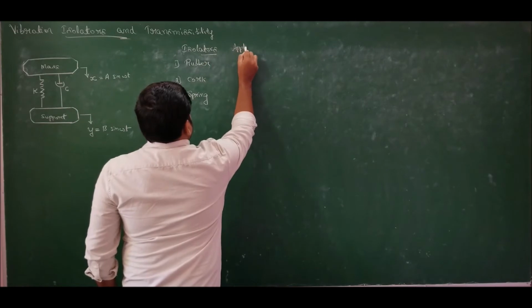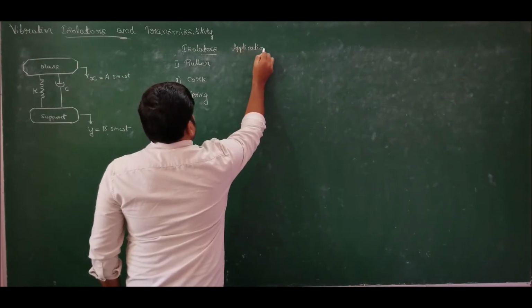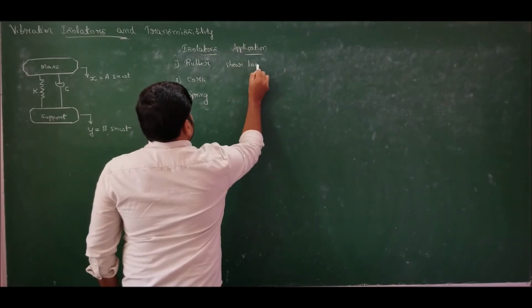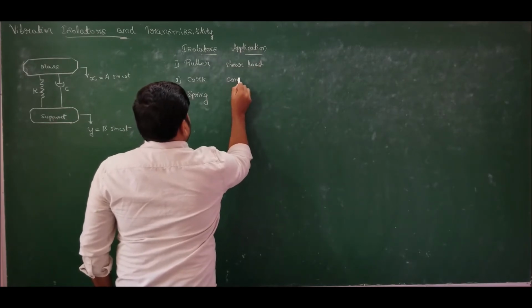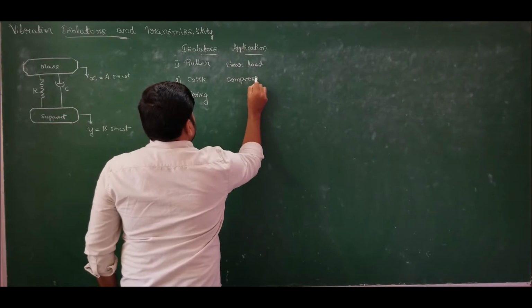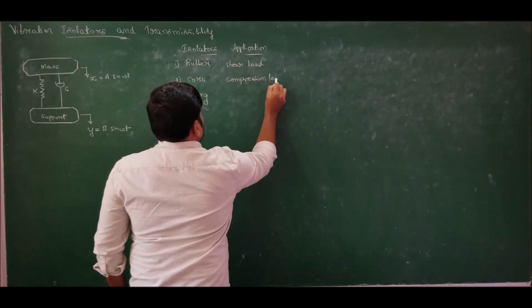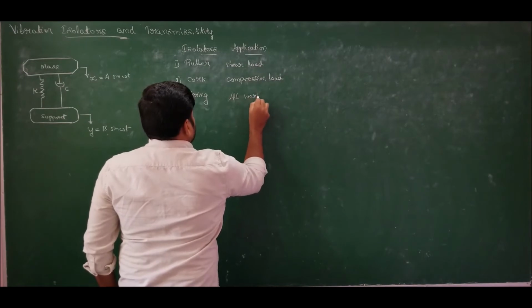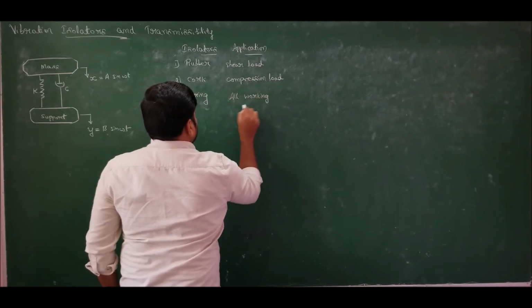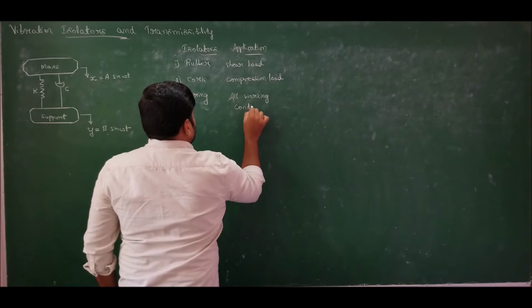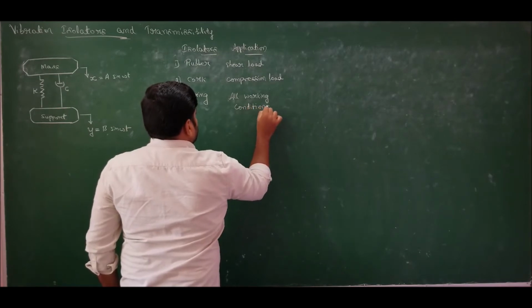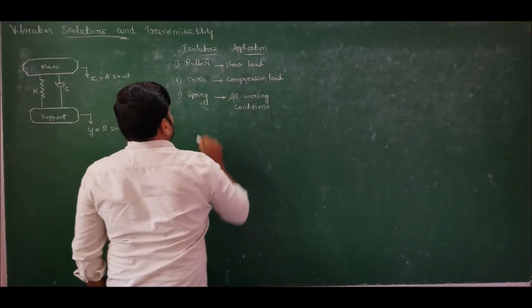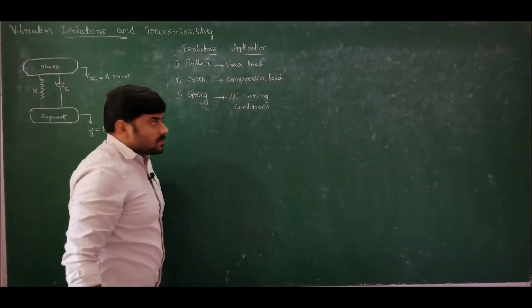Rubber for shearing load, cork for compression load, and spring for all working conditions, including high frequency ratio applications.